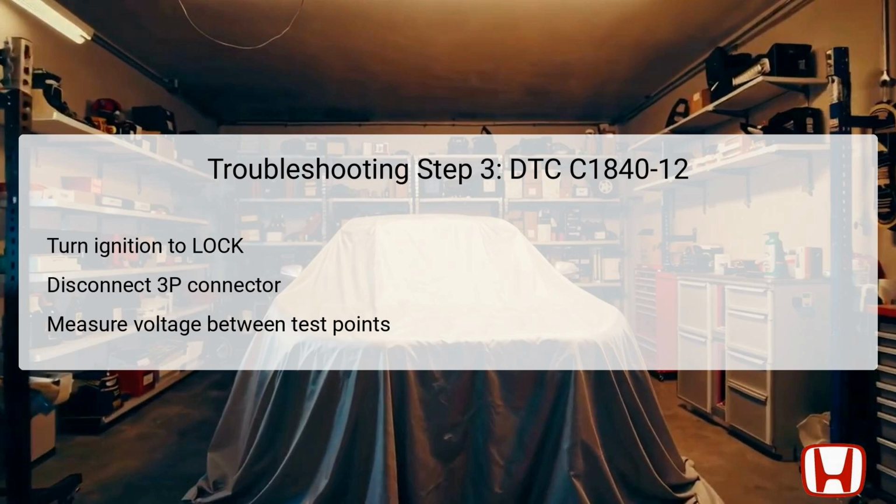This measurement will help determine whether the voltage is at or above the threshold of approximately 4.14 volts. If the voltage is confirmed at this level or higher, it indicates a potential issue related to a short to power in the PS1 line, prompting you to advance to the next step in the troubleshooting process. Should the voltage be below this threshold, further diagnostics must be executed.